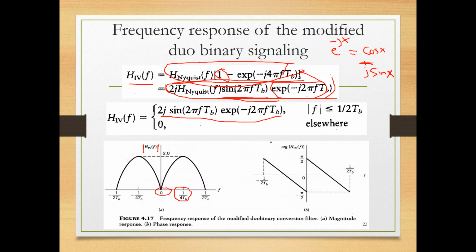And here, this is the phase shift. How do you find the phase shift? The tan inverse of the imaginary value over the real. So here you have an exponential, and you convert this to rectangular form. This is polar form. This is like the amplitude. This is the amplitude, yes?